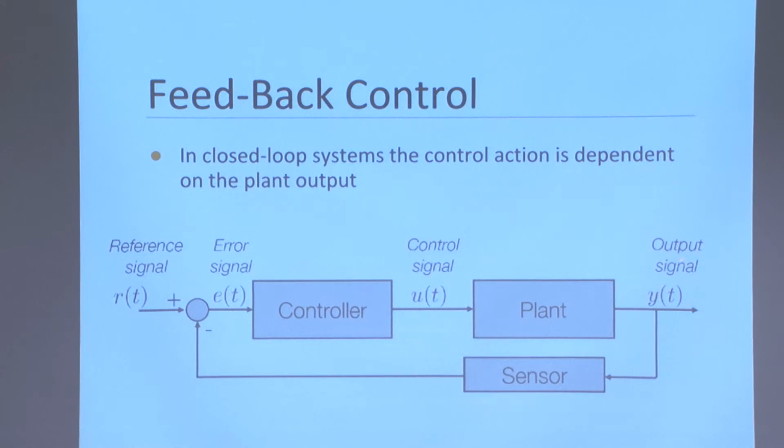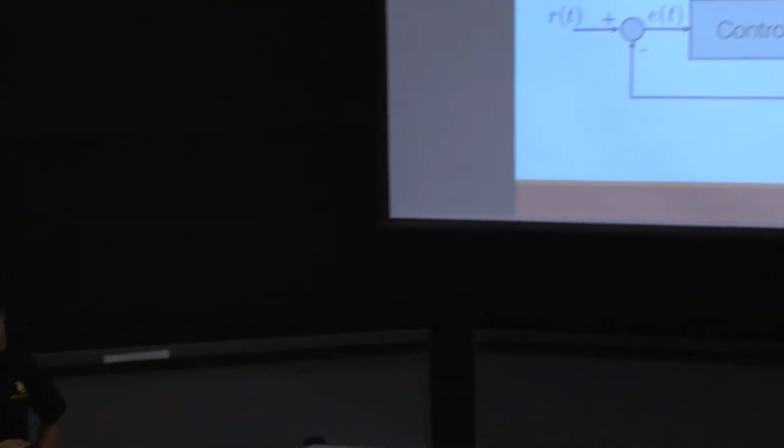We're going to look at what is the current state of the car and what is our desired state of the car, and we're going to subtract the two. This is going to give us our error signal. This is, is the car going 5 miles per hour too fast or 5 miles per hour too slow. So the error signal is what gets fed into the controller.